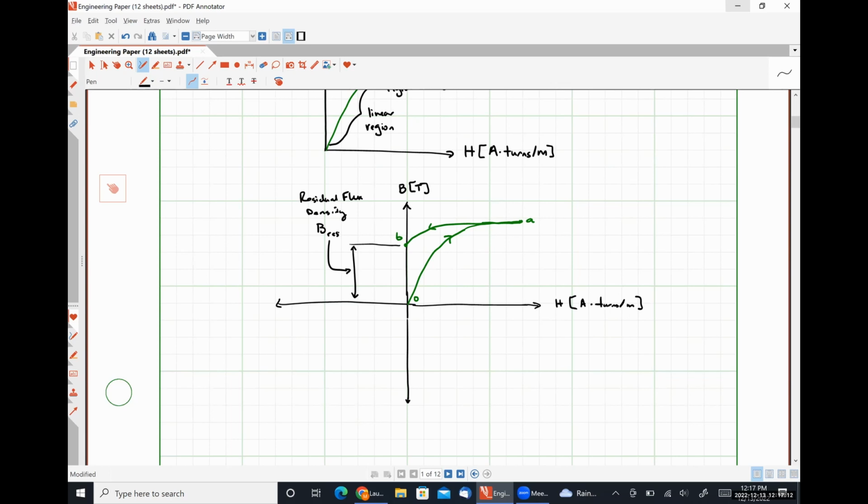The material is still magnetized. So effectively, we have turned a raw magnetic material into a permanent magnet. This is literally how you magnetize materials in industry. You put it in the presence of an electromagnet, drive it into saturation, and then turn your current down, and it retains some amount of residual magnetism. Therefore, your device behaves like a permanent magnet.